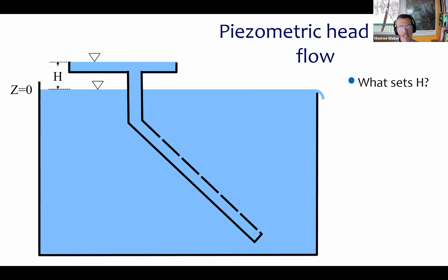What if I increase the rate of droplets going in? What's going to happen to h? Okay, it's going to spill over because I didn't draw the tank any taller. But if I increase the flow, h has got to increase. What's causing all that head loss? What's causing h? It's the head loss going through the pipe and coming out the orifices. So h is set by the flow rate and by the head loss through those orifices.